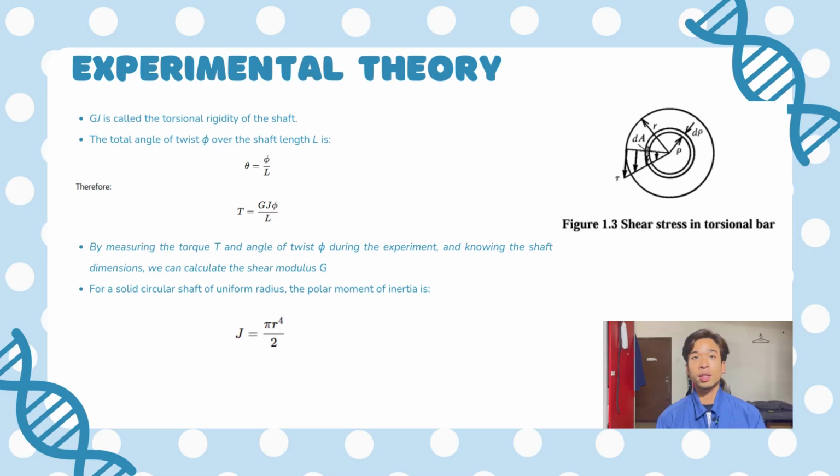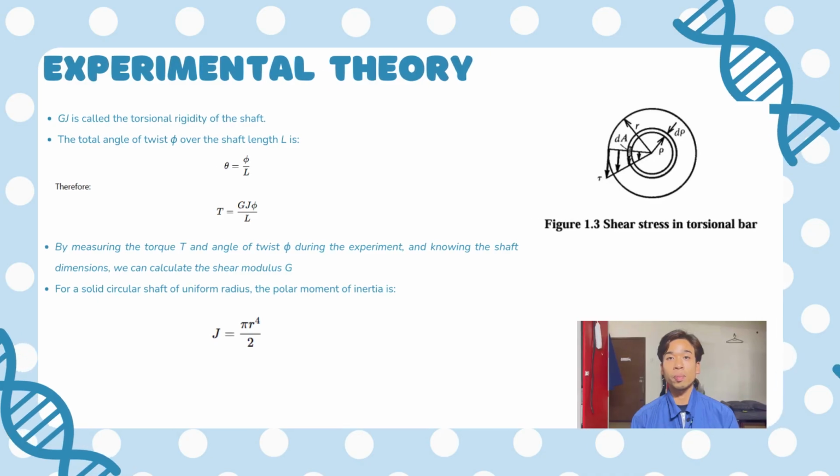The total angle of twist psi over the shaft length L is theta equal psi over L. Therefore, T equals GJ psi over L. By measuring the torque and angle of twist during the experiment and knowing the shaft dimensions, we can calculate the shear modulus G. For a solid circular shaft of uniform radius, the polar moment of...